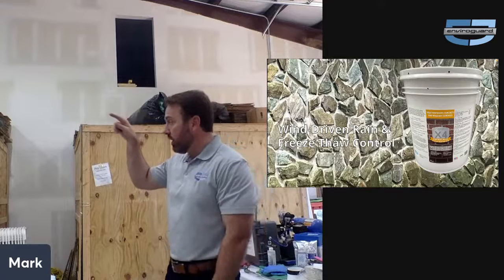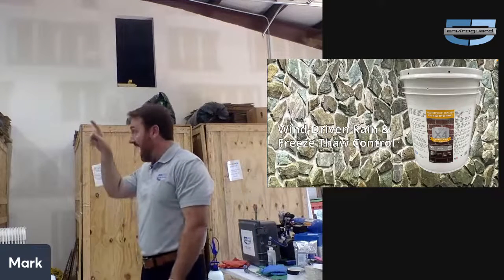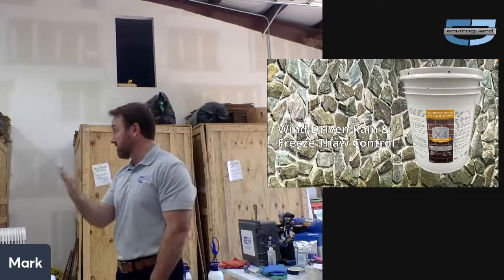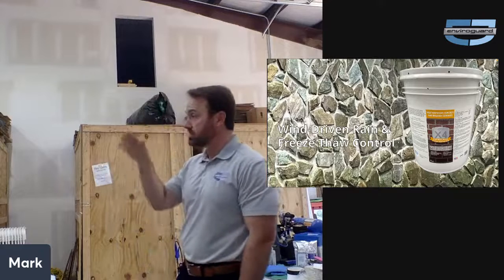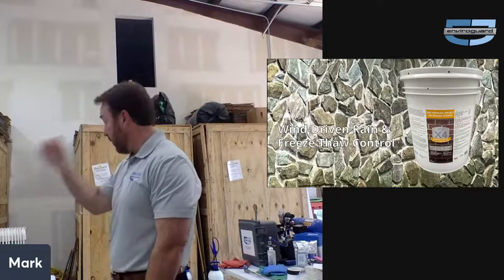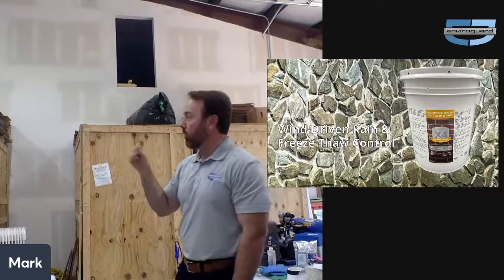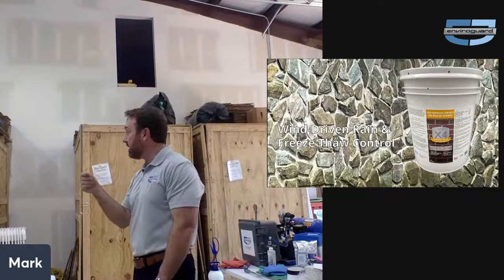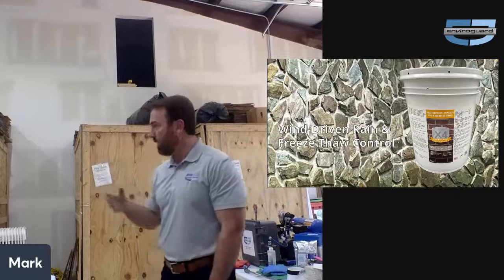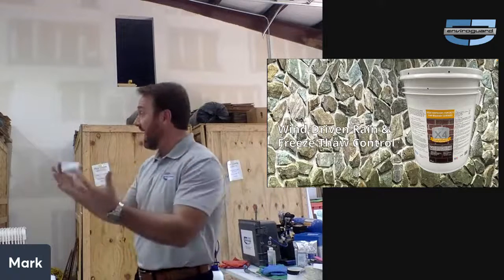If moisture wicks into that surface, and the test is a 20-minute test, and all the moisture goes in, you've got a super porous surface that's absorbing a lot of moisture, which means that the life expectancy of that surface is going to be dramatically impacted by moisture. On the other side of it, your ongoing test is the same sort of thing, so that you know when to retreat as well, 7 years out, 10 years out, whatever it might be, if you maybe turn this into some sort of an annual inspection program.